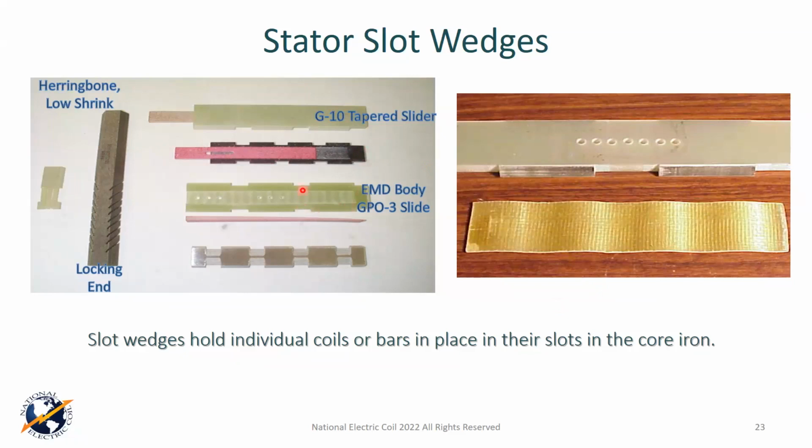And you might want to ask, well, what are these little notches we see over here at the side? Well, those notches are to allow the air vents to have complete circulation and so on. You see that on a lot of these. And usually they're tapered a bit, because a lot of those vent passages are oriented towards the direction of the rotation, so that it draws the air up through, and you don't want to obstruct it. So there's a couple of different things you see there. And obviously these areas that you see in between those vent areas, well, those are the areas that engage the core and allow the compression of this wedge to keep everything nice and tight.